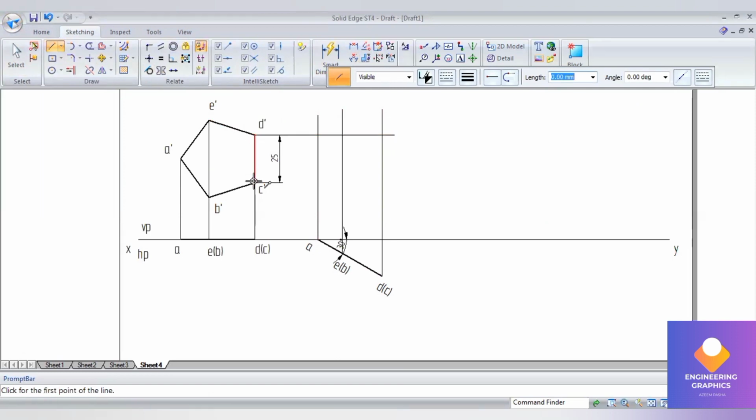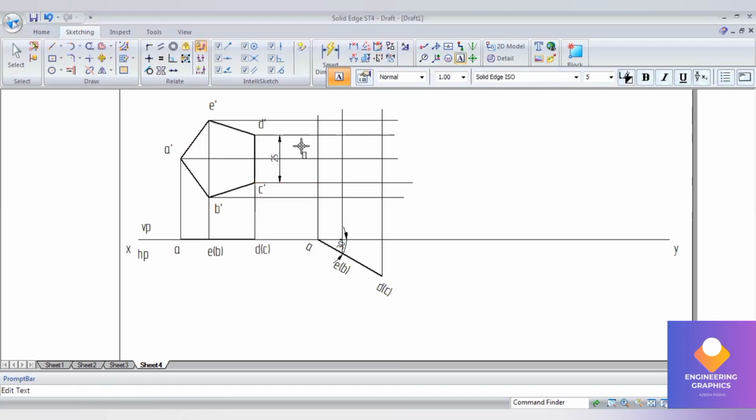Horizontally also you draw the projection lines. From each corner end you have to construct the projection lines. Now write down the notations properly. Wherever the top view and front view projections intersect, you need to write down the notations with respect to each end.